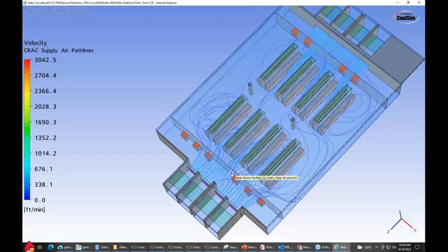They don't watch the rack rails around the perimeter of the rack. A big area of concern is under the rack, making sure it's sealed under the rack, make sure the perimeter of the rack is sealed against the contained area, and then within the rack, making sure the rack rails are sealed on top and on bottom and on sides, and all blanking panels are in place. In other words, the risk is higher of operational problems in these designs because there's no way to compensate, no way to modulate the supply air.